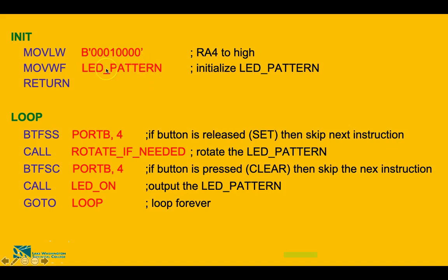So when you move this literal number into this general purpose register, then what will happen? Your RA4, which is your LED4, RA4 is your first LED from the right, that will be high. That's why you are using this, and it says then return.